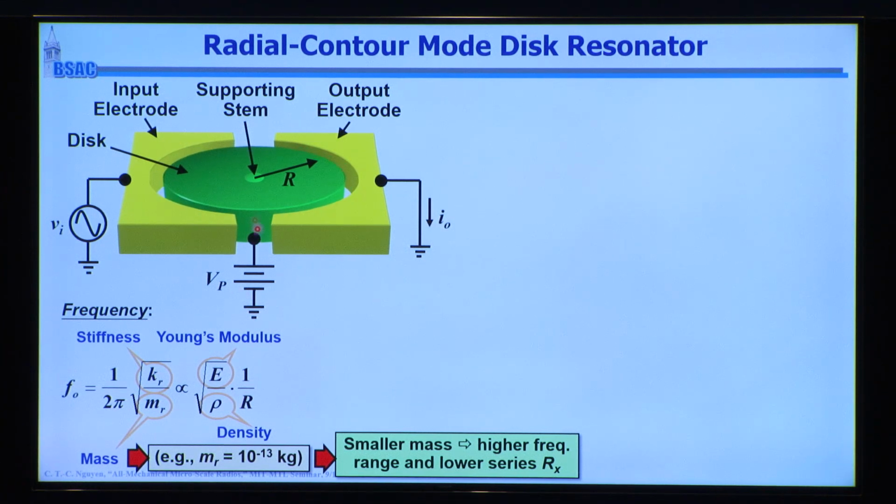So the way that you operate this device, the way you get it to move that way, is you put a voltage on the device. You're really just putting charge on it because there's no current path here. So there is no DC current flowing, no power consumption. Okay, then you put an AC signal, and this could be your RF signal. That would then drive this with a force that's proportional to this bias voltage and that AC signal to make it move at its resonance like this.